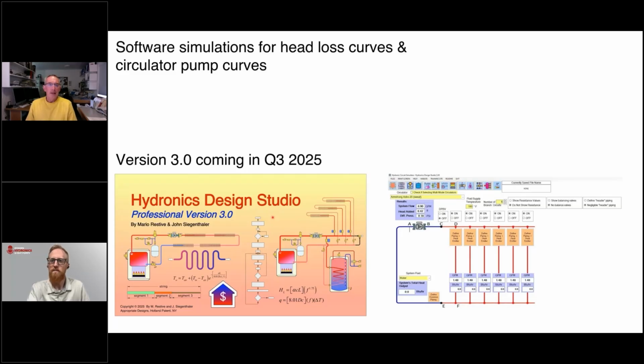Okay, well, that kind of goes back to what is the expectation of the circuit. A common way to do it is to say, all right, I want my circuit to deliver so many BTUs per hour. I'm going to pick a number, 40,000 BTUs per hour. You've done the heat loss analysis of the portion of the building that this circuit serves, and you've determined under design load, I need 40,000 BTUs per hour.